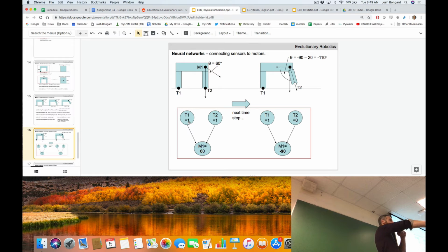We're now applying flexion force in the other direction to pull it back in. So it's slowing down in its forward acceleration because it's about to start going the other direction, but we're not there yet. So the front leg is by definition still off the ground. Let's assume that the back leg is still on the ground, which means the input layer, even though there's change in motion of the robot, the front leg is slowing its extension acceleration. Even though there's change in motion, there's no change in the input layer. It's still 1, 0. Back leg's on the ground, front leg is off the ground.